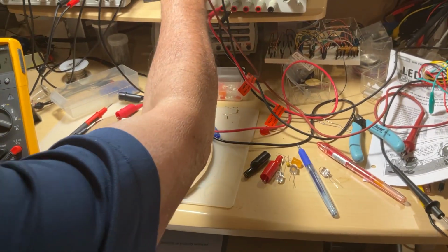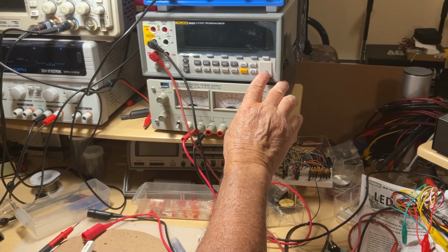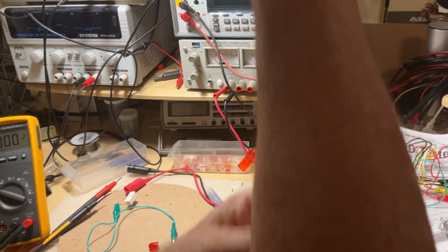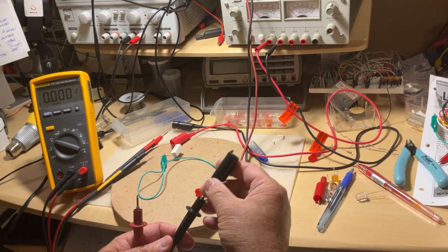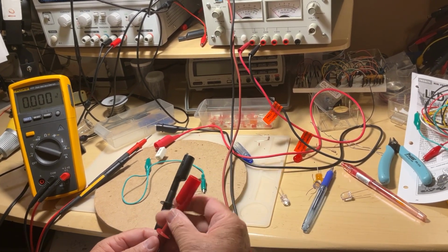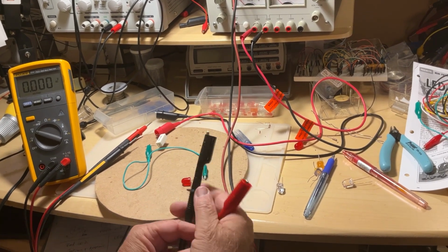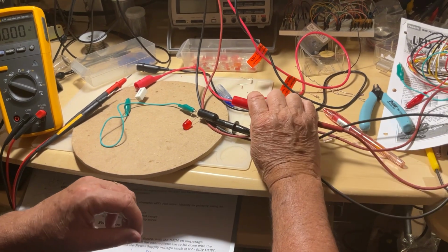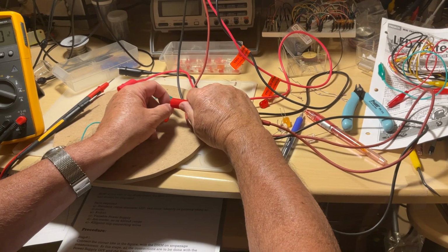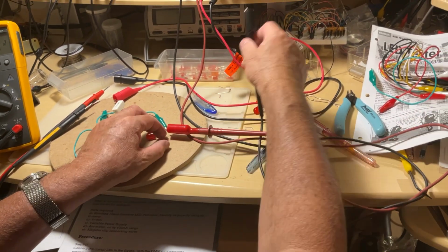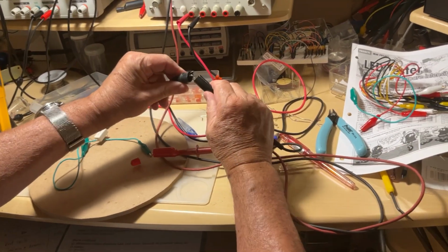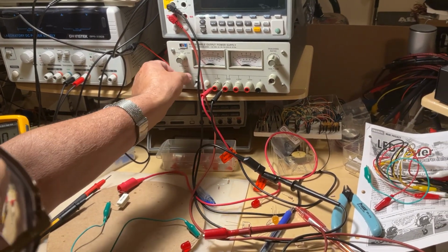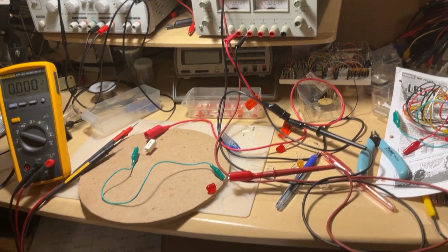Next, the meter has to be put on amps, and I just said on 400 milliamps, okay? And then the two leads of the meter, we're going to place alligators on them as well. And now we close the circuit to the other power supply lead, which is this one, like that. So no other parts around, and the power supply is at 0, you just check the knob is completely counterclockwise. Okay? And here is what we're going to do.